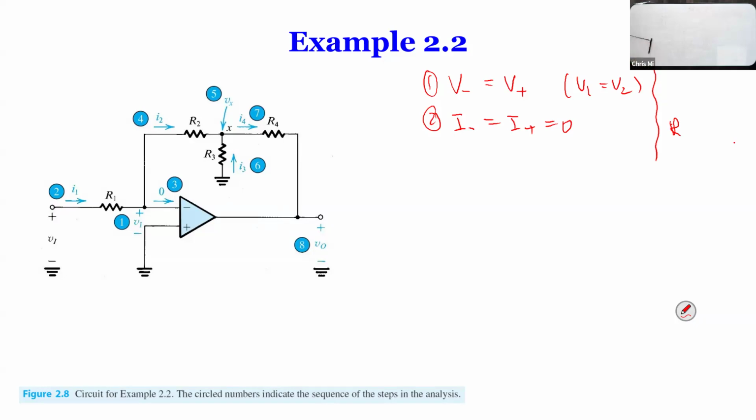What I'm saying is here. You see, there's nothing connected here. If there's something connected here, that will be considered a node. But there's nothing connected here, so this is basically lying together. So you see a dot here, but it's not a node. So ideally, this has two nodes. But we can further simplify this to one node.